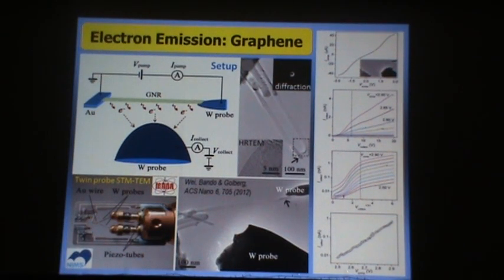If we use this double probe system, it means in total we have 3 contacts, 2 movable and 1 stable. And if we take a graphene nanoribbon, shown here, it has just 3 layers, we can do these interesting experiments. We can use a third probe as a collector of electrons and 2 probes as a drain and source.